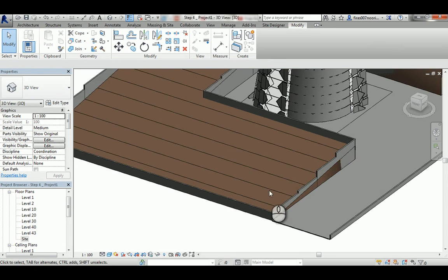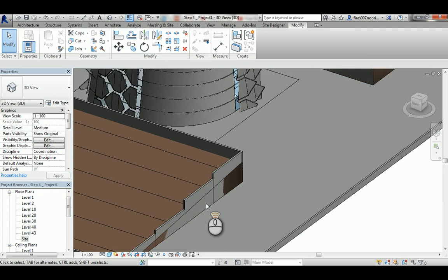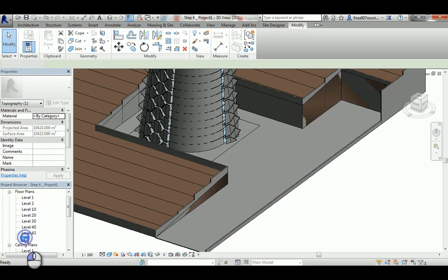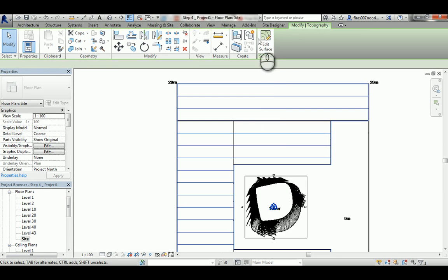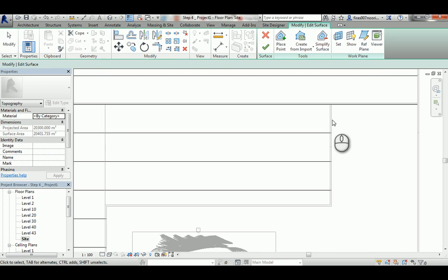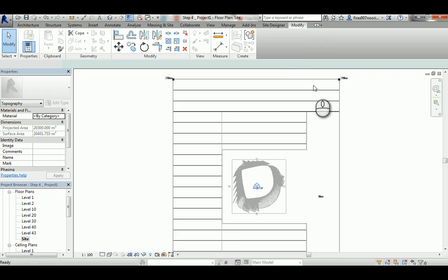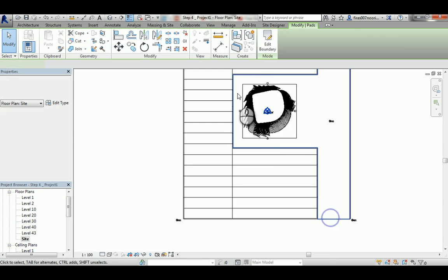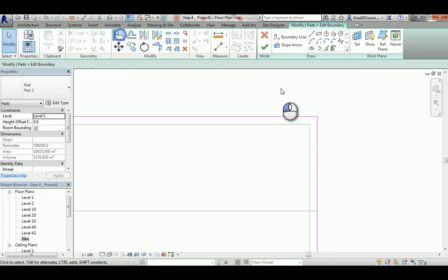Now, if you noticed, the mud is shown here, it's pretty ugly. So I'm gonna go back to the site again and fix this. Just edit surface, and actually you can just push the wall slightly that way, or you can make the podium slightly bigger. So probably I'm gonna go to the podium itself rather than to the mud. See here, I can just align to this.